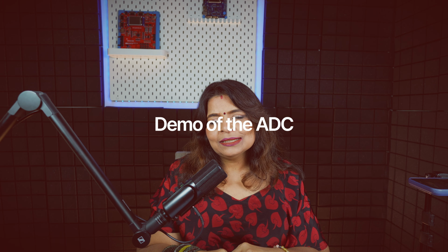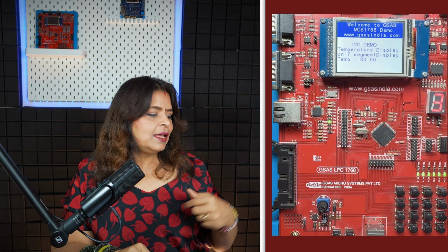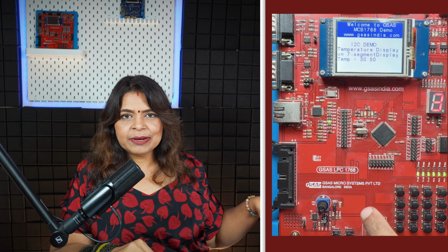So let's start with the demo of the ADC. As everyone knows, ADC is an analog to digital converter, so you need some analog input to be given to an embedded system. In this demo, I'm again using our GSAS LPC1768 board, and the board has an onboard potentiometer. Through that potentiometer, I'm giving the analog input to the on-chip ADC of the LPC1768, which will convert it to digital data, and the digital data can be seen on the onboard LCD display.